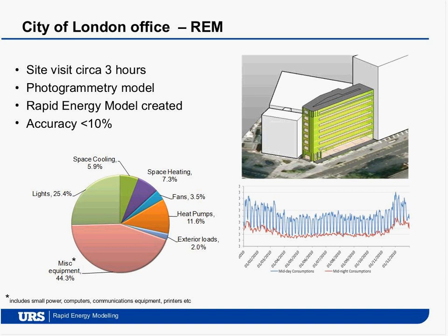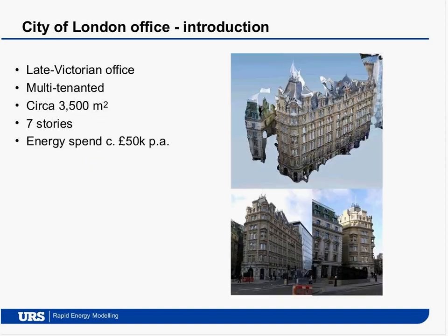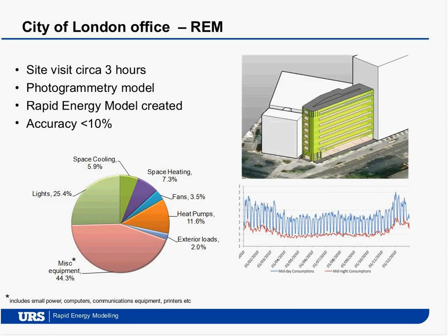The building is heavily overshaded. It butts right up to other buildings on two of its faces, and the remaining face, the street elevation, is north facing, and the glazing area is very small, so it's got a low glazing ratio. So you would expect that daylighting opportunities are limited, and lighting is on most of the time, so it is a significant consumer.